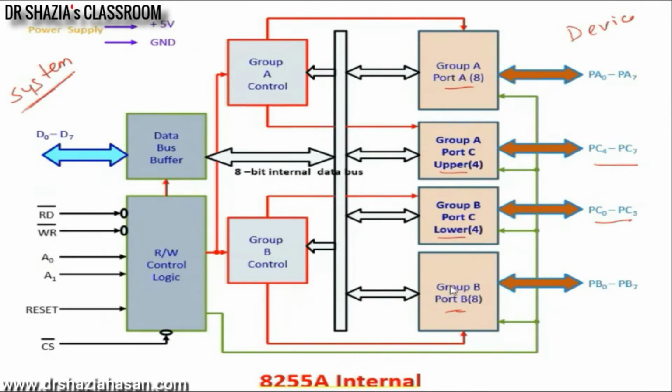But this device is connected to which particular port, and always the port is identified by its address: IN AL, 08. So 08 is the port address through which you want to get 8-bit data onto your accumulator. Yes, or OUT 08, AL. You are sending data AL to a destination with port address 08.